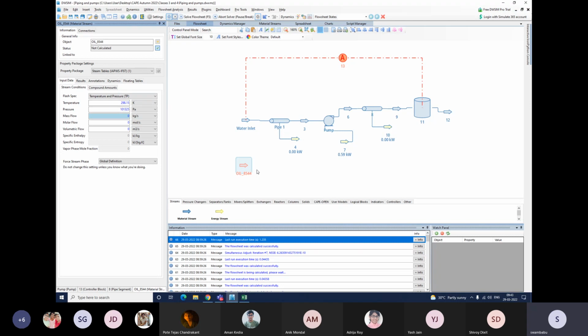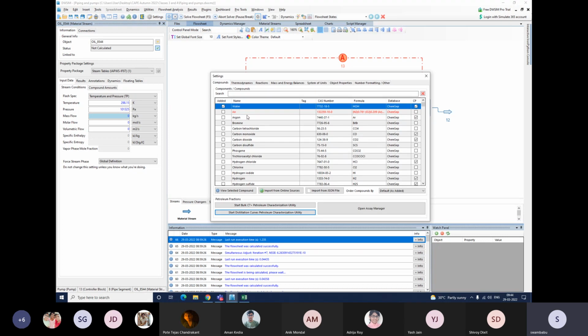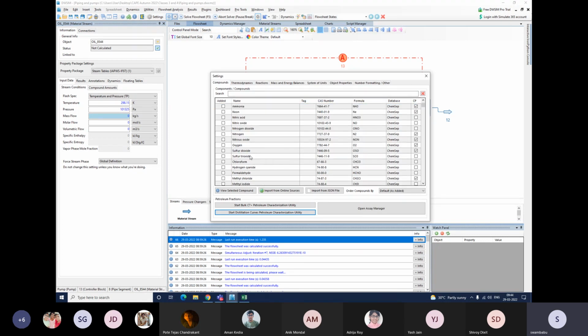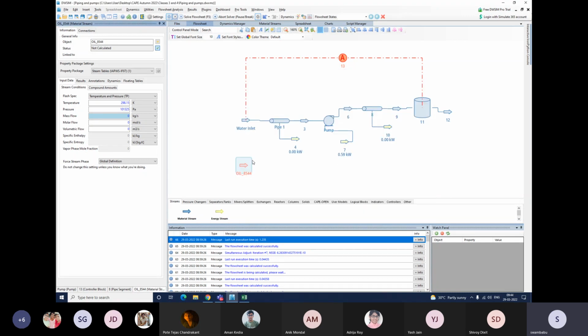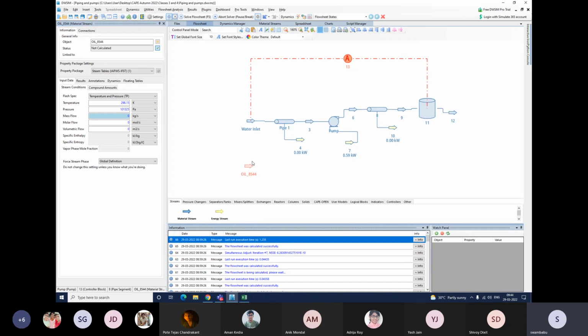Now we can do distillation or reaction or whatever. Of course, we want to do hydrotreating and other things. We can even do reaction, combustion, or heat it. So for all processing, if you want to process crude oil, we cannot define it directly using this skeleton because this is not a single component. This is a combination of many components. Because of that, we need to define the oil stream or crude oil stream using this TBP data.